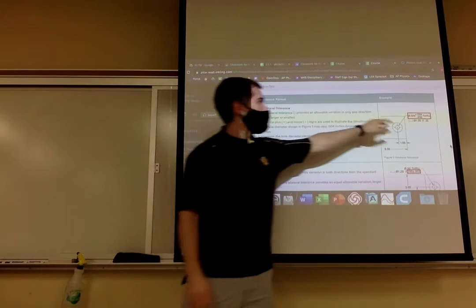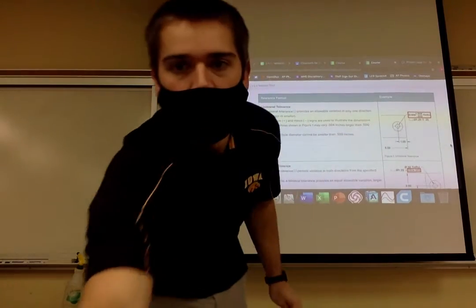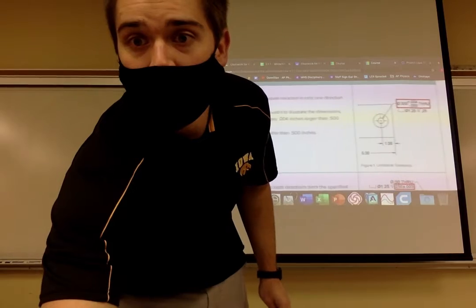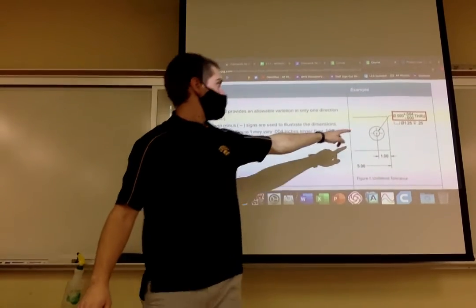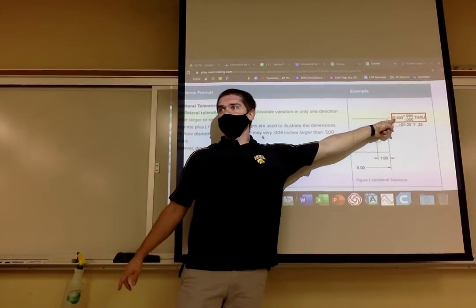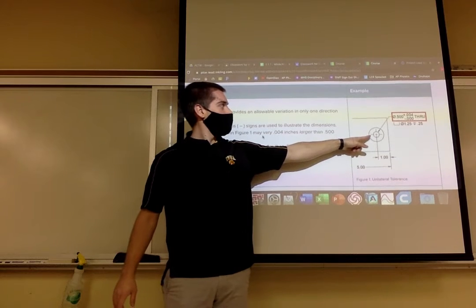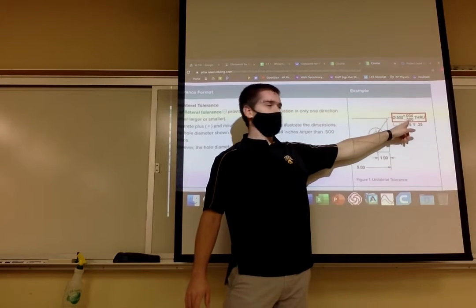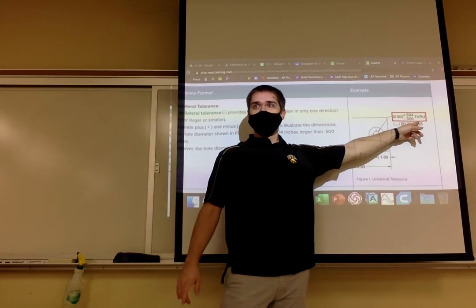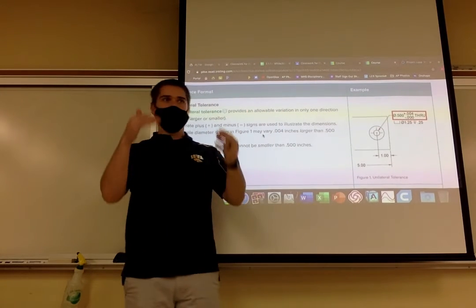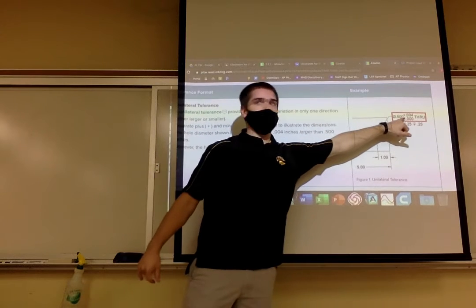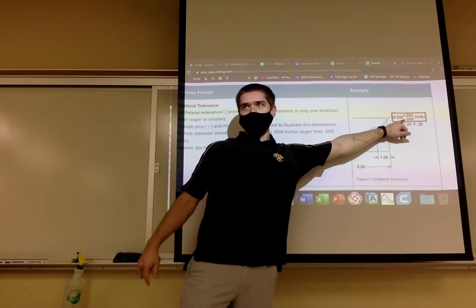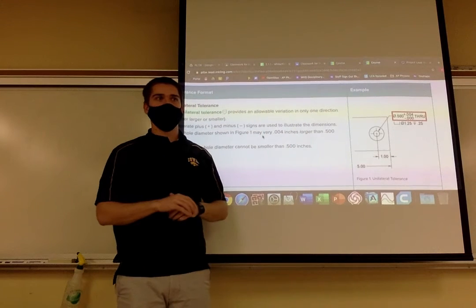Now, if you look over here, this is how we write them. Is that visible? There's a tolerance, right? The dimension is right here. The diameter of this hole is 0.5 plus 0.004 minus 0.000. Do you see how anything less than 1/2 inch is unacceptable? They gave no tolerance in the negative direction.